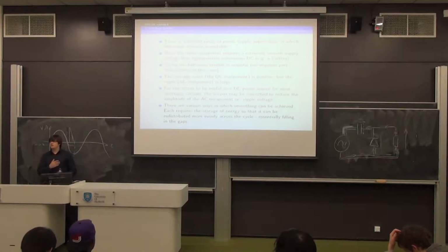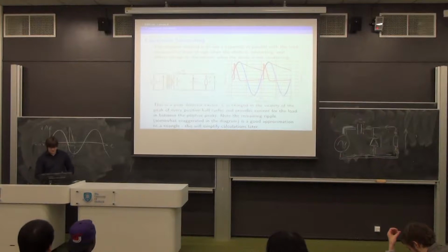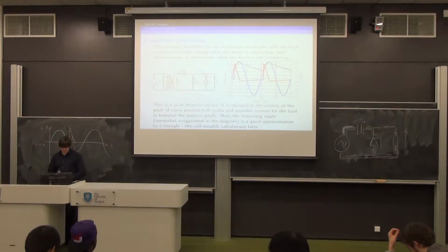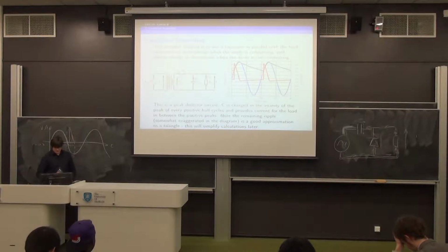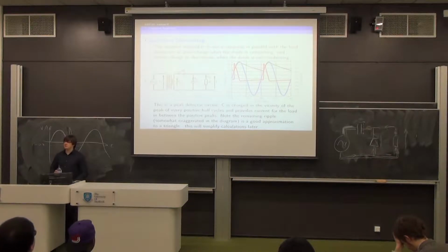Now, it's never less than zero, but it spends half its time at zero, which isn't really very useful. So what we really want is to fill in the gaps. And we can fill in the gaps with a capacitor. So this is a peak detector driven by a voltage source, essentially. The transformer is only there as a sort of extra to make it into a power supply.